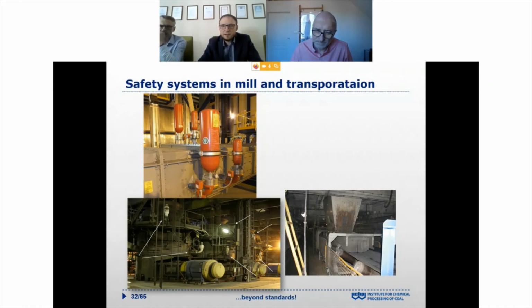It is a system where the fire extinguishers are connected with the detection system, and in case of explosion detection, if the pressure is increased inside the mill, the system initiates the injection of specific solid particles that avoid the explosion.